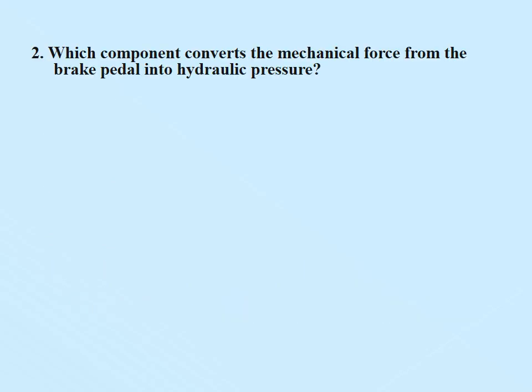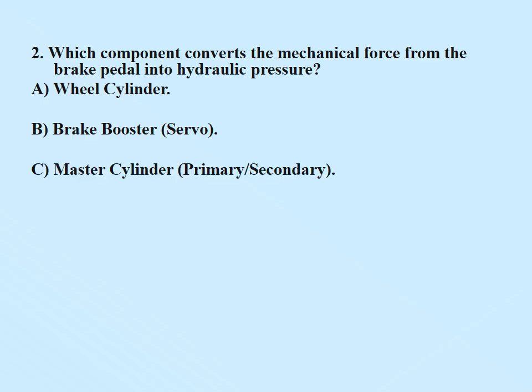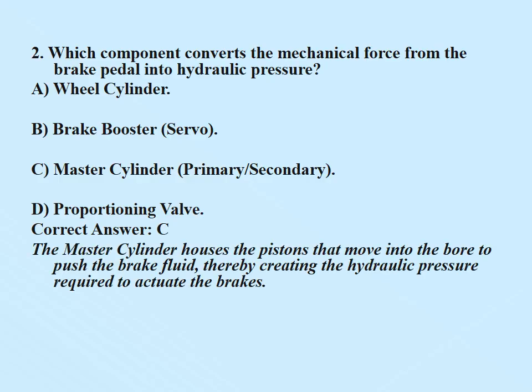Which component converts the mechanical force from the brake pedal into hydraulic pressure? Wheel cylinder, brake booster servo, master cylinder, proportioning valves. Correct answer is C. Master cylinder, primary and secondary. The master cylinder houses the pistons that move in the bore to push the brake fluid, thereby creating the hydraulic pressure required to actuate the brake.